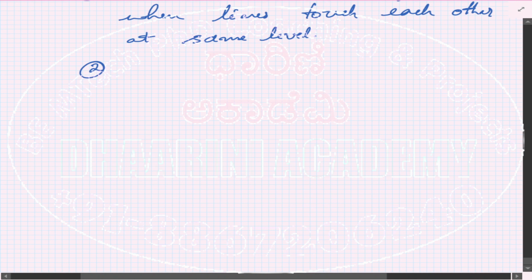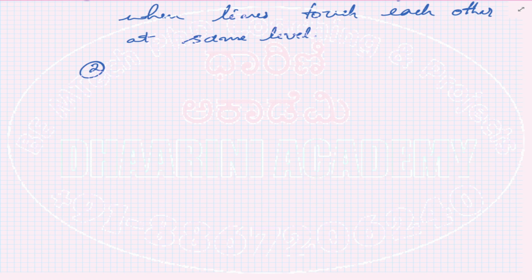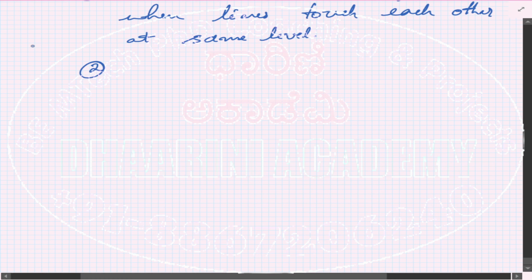Okay. Next, if you have two different layers, polysilicon and a diffusion, and if they cross each other, it means there is a transistor. This is possible even for a second layer, third layer, or whatever number of layers. So we should take care that only in whichever position you expect a transistor, polysilicon crosses diffusion. Very important. Most of the time we make mistakes over here.